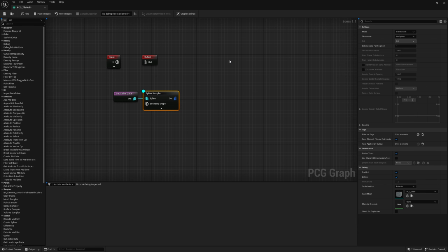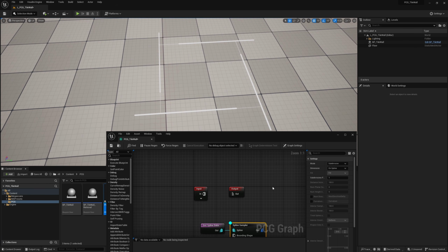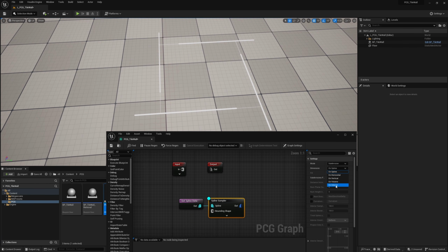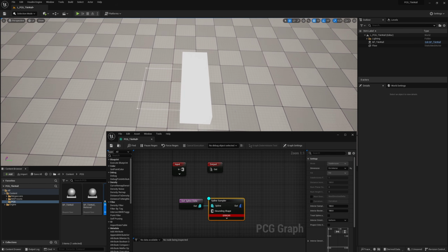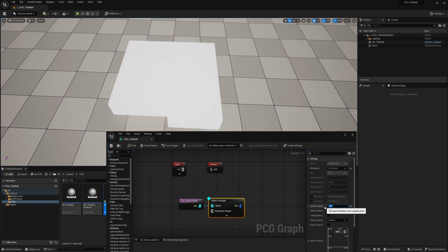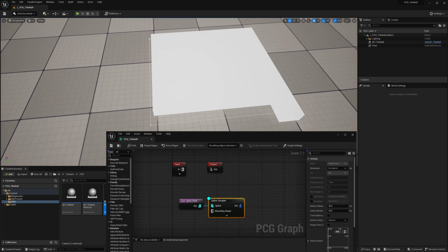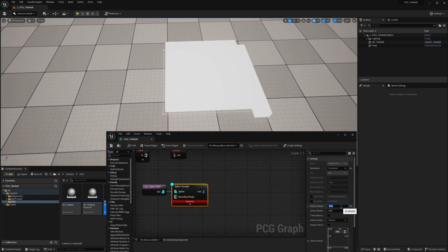And in here, if we preview it, we can see the points are on the spline itself, but we don't want that. We want to be on interior. So we select interior and immediately you see the large points in here. The points are way too large. I'll go ahead and change the interior sample to something maybe like 30. Interior border also 30. It's better, but it's still quite large. So maybe something like 20 and 20.